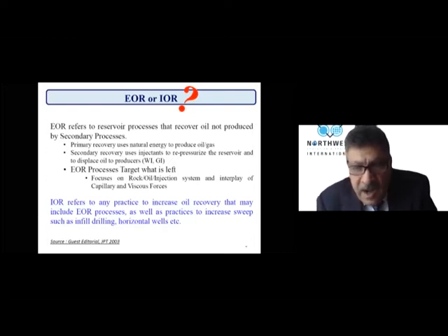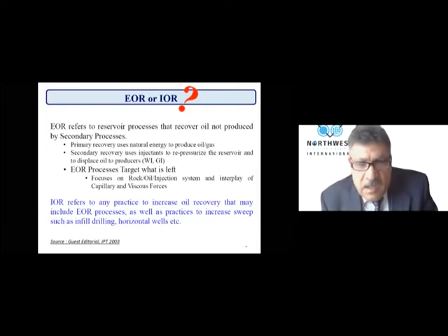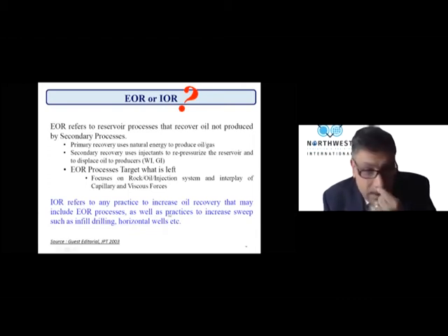How can I increase oil production? Either by water injection, water flooding, gas injection, or maybe by using an ESP, electrical submersible pump, or a rod sucker pump, or gas lift. So that is IOR, which is more general, covering both.